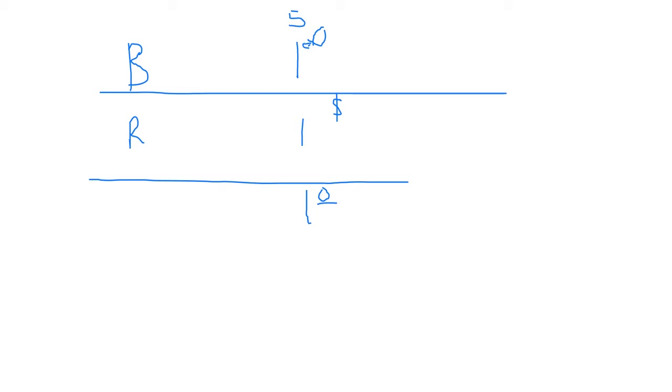Now, we've managed to read the state of the pin, so we get the current state of the pin, and then we want to put an inverse, which is a NOT gate. So first we do an AND and then we do a NOT. So we read the state, we have a 1. We do an inverse, we get a 0. We read the state, we have a 0. We do an inverse, it will be a 1.